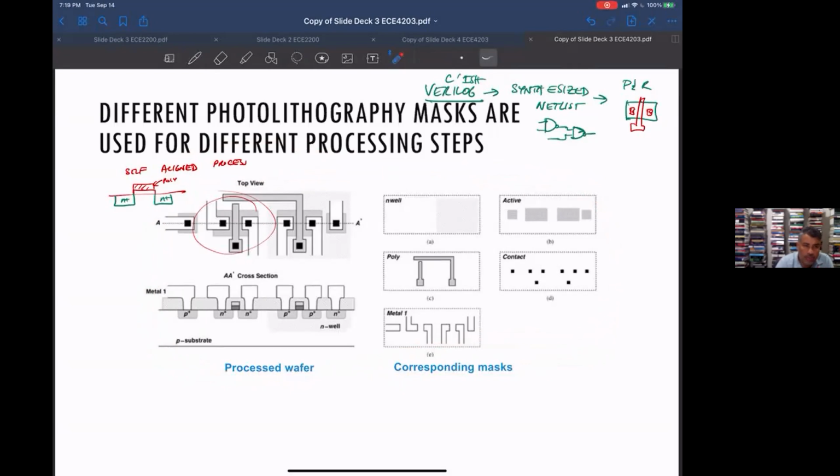If you've got a 40 gigabit per second Ethernet output out of your chip, that's going to be designed by hand by somebody. These place and route tools typically work in the hundreds of megahertz clock rates. They're not going to take you to 2-3 gigahertz or higher.